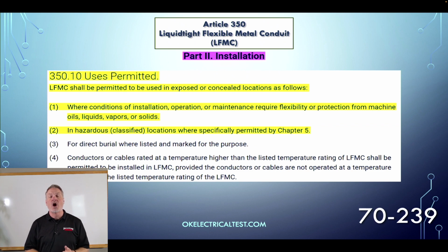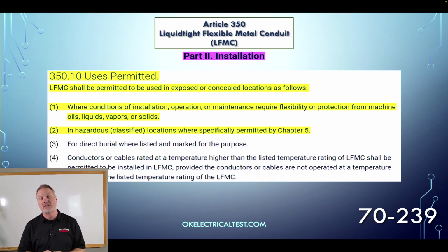All right, let's go to Article 350, LFMC. One of the questions that we see commonly on the exam is, what does LFMC stand for? And that's liquidtight flexible metal conduit. Moving down under there, under uses permitted, dot 10. Notice we're still following that same numbering system through the conduit and tubing, right?